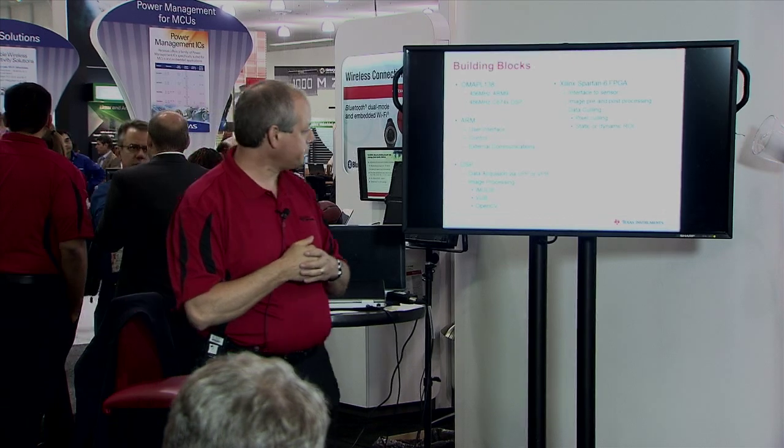So you can run about 150 megabytes per second into the uPP interface, right into the DSP and the ARM. You can direct DMA that data right into SDRAM without processor intervention. So it's a real handy interface, and a really good interface for interfacing with programmable logic and other devices that have a parallel interface.